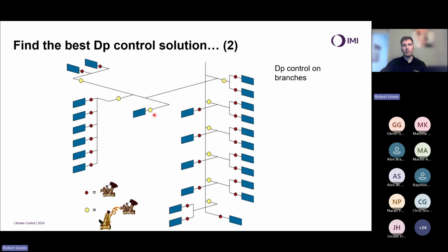And again, we could say we're only interested here, but if we placed one here, we would need to place one on every other sub-branch. And all of these would be required to be set up and commissioned correctly. But the beauty is, if I was to set this one up, when I do any adjustments here, or here, or here, they will dynamically self-adjust and maintain their set point so long as there is sufficient available head and volume to satisfy the complete circuit.